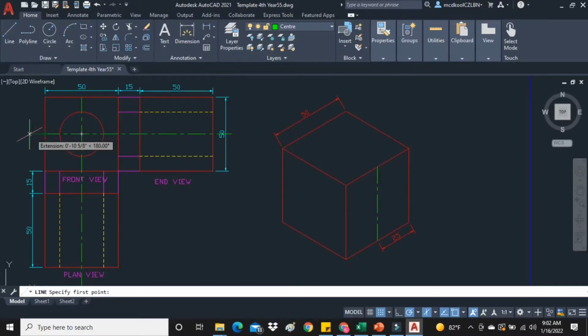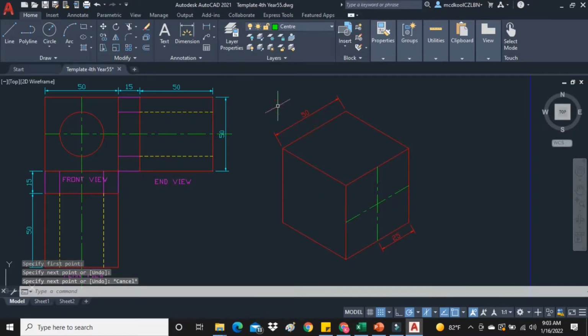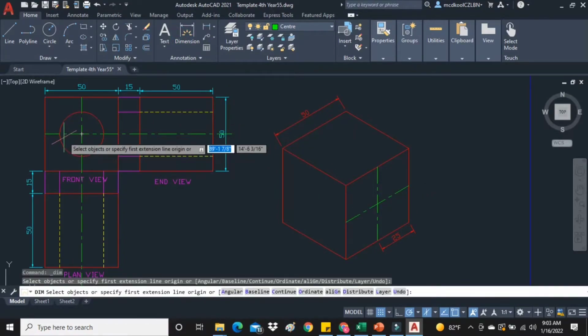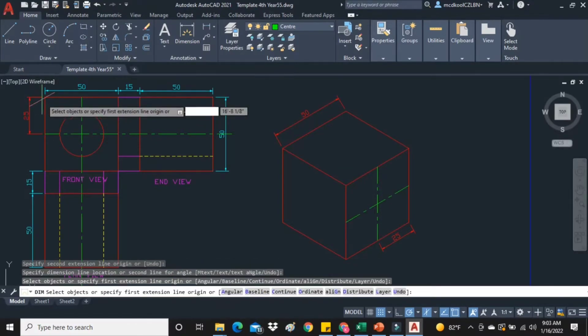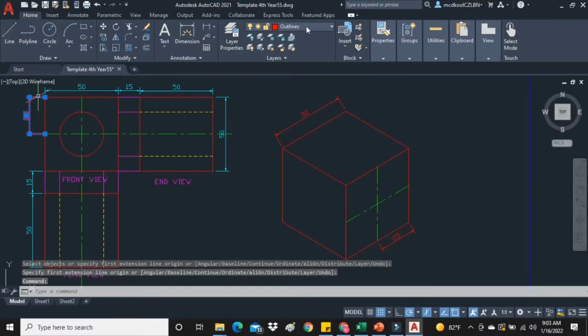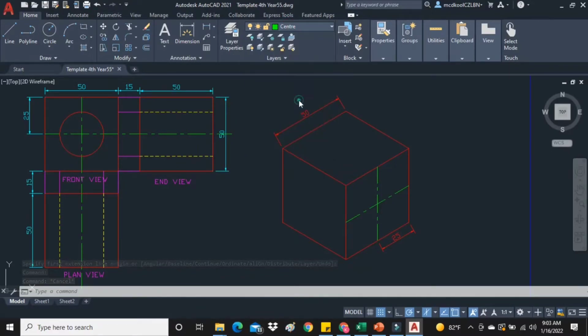So we're going to draw the horizontal center line now, the one that goes across. So I've found the midpoint and I just project it across, and I'll just check the measurement to see if this line is indeed at 25 millimeters in the middle. So just checking the measurement, and it is 25 millimeters. So the midpoint is correct.